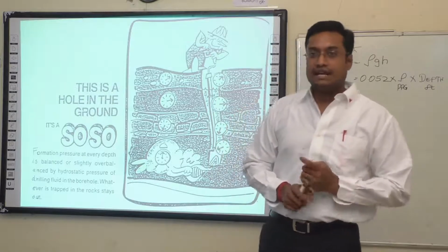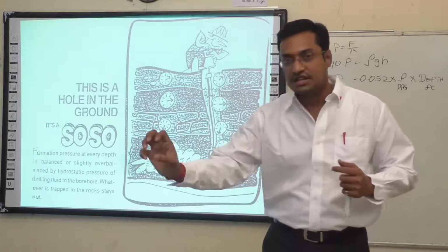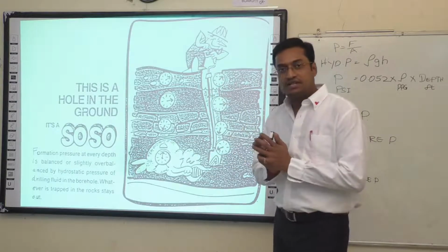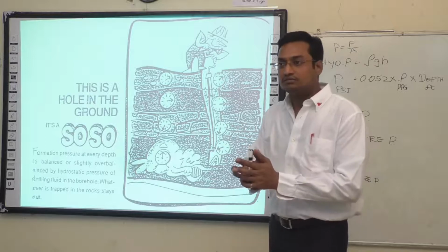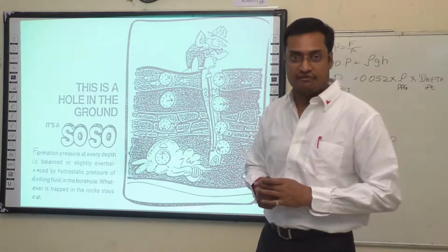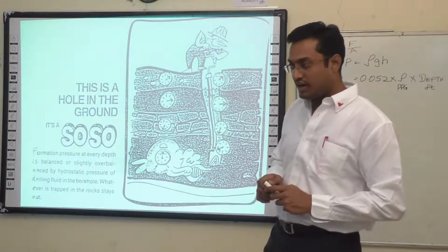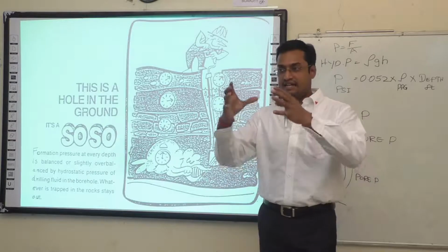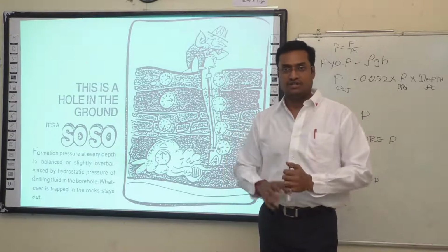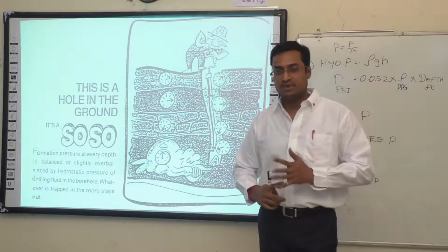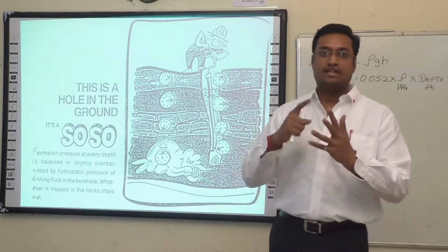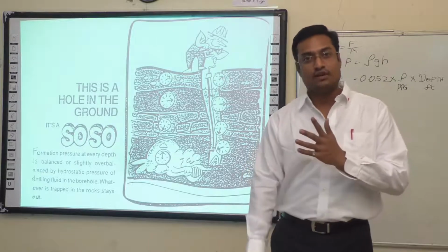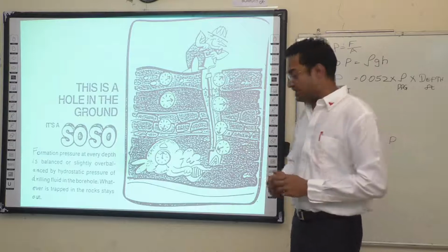So when we reach the target depth, or when we reach the reservoir, where we have the hydrocarbons, oil and gas, the hole size normally preferred or required is 8.5 inch. So one of the objectives of drilling is to end the well in an 8.5 inch section, so that we have more equipment to do all the logging, all the testing, and we can produce in a better way. We have options of deepening the well if required at a later stage.